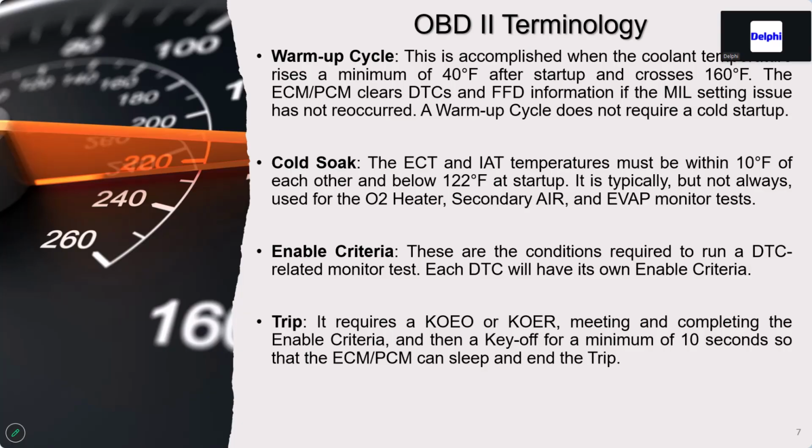But remember, a trip does not end until you turn the key off. And I always say a minimum of 10 seconds, but the simple way to remember is if your scan tool says no data available, that trip is ended. If you don't do this and you start the key up right away, you turn it off, and within a few seconds you turn it back on, the PCM hasn't gone to sleep, you're going to be wasting your time because you are in the previous trip and you may have hit the maximum time already and you may have exceeded the criteria at that time. You can't make it work. So keep these 4 things in mind.